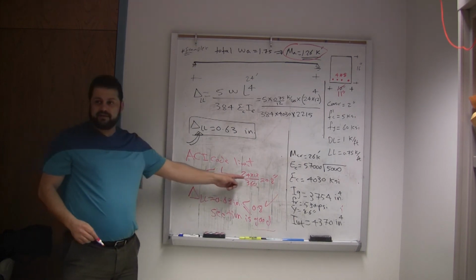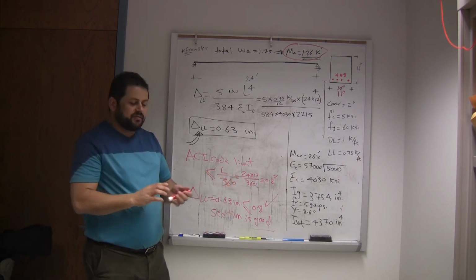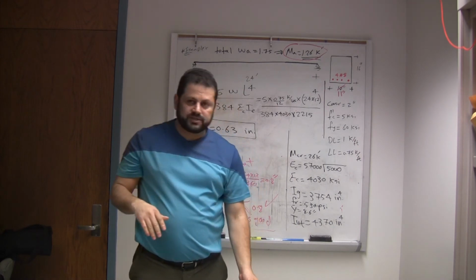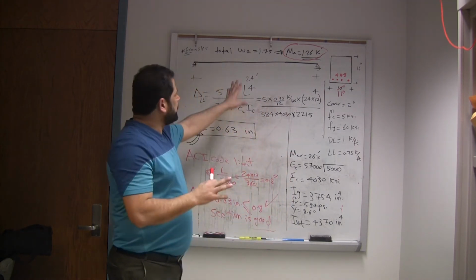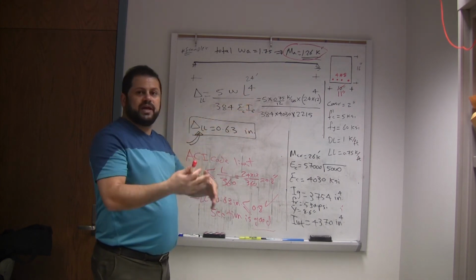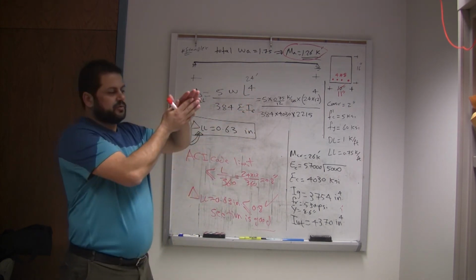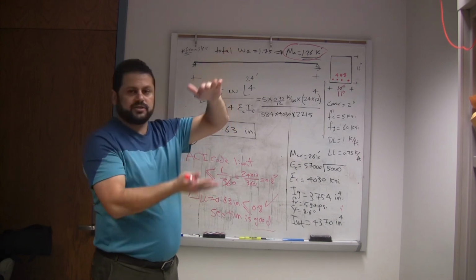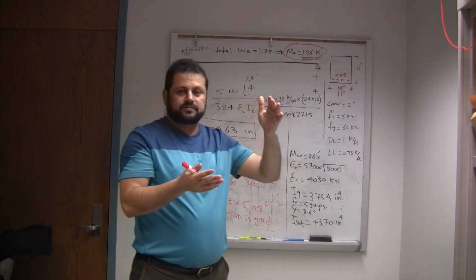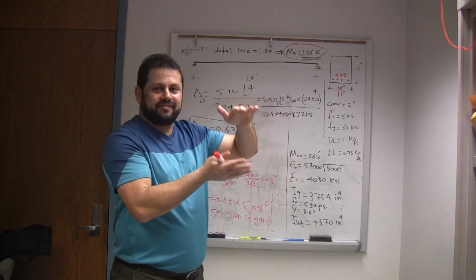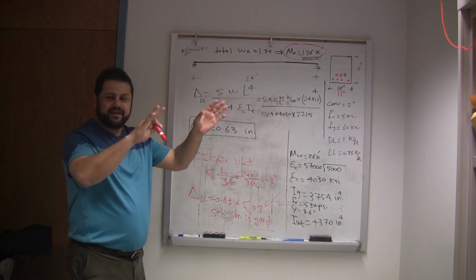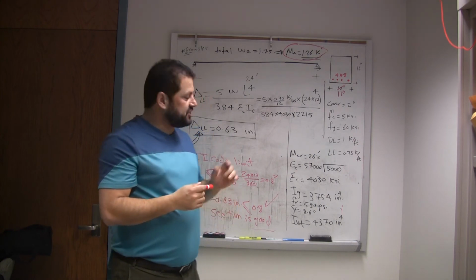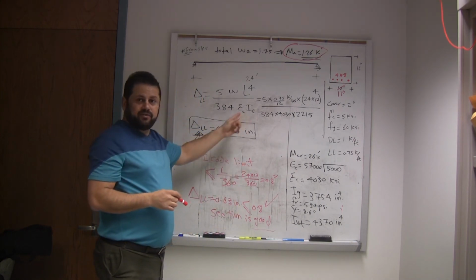The deflection is fine. So guys, look, I know some of you, when you're seeing a design project in some places, try to make sure your beams are fine with the deflection so you don't have to check it. So you keep squeezing or increasing the floor thickness. You don't have to. It doesn't mean that the deflection is bad. It means the deflection needs to be checked. Some software will give you a red flag on the deflection: check the deflection due to live load.